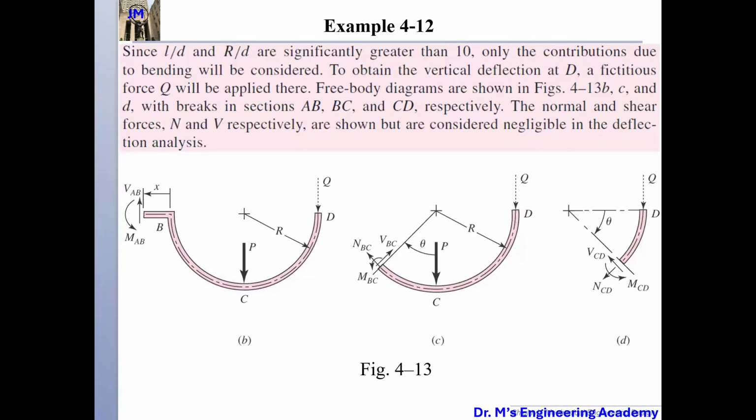For example, if we use R and theta to describe this curve, how can you use R theta to describe this one? It's impossible, right? That's the reason we just carve it here. So this is my first segment, and then, as I said, whenever you see the concentrated force, always carve it at that point. That's the reason we have this one and we have this one.